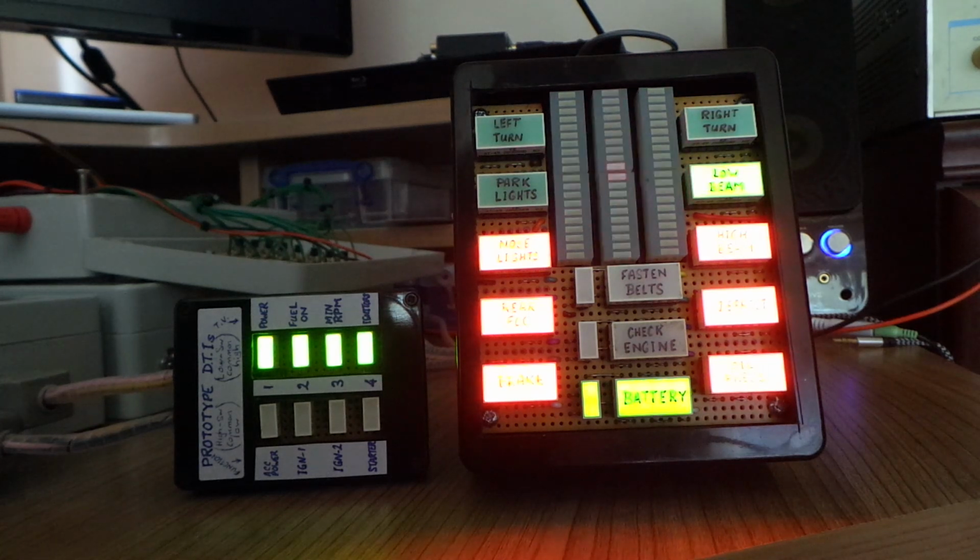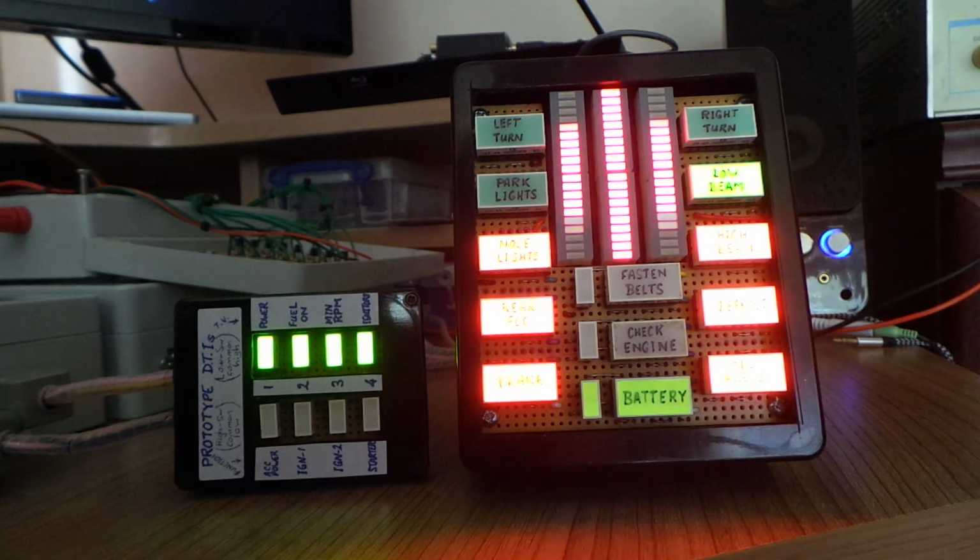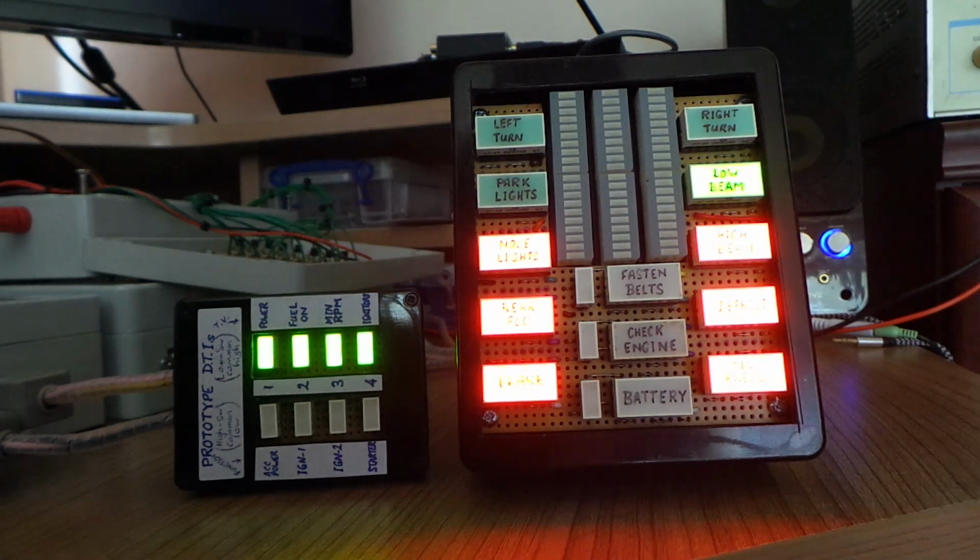So when you first put your ignition on and the engine isn't rotating, so the alternator's generating no voltage, you will see that battery indicator illuminate, because of course the alternator voltage is 0, but the battery voltage has some definite voltage. As the alternator starts to generate a voltage, it brings up the voltage it's generating, and when it eventually matches the battery voltage, the battery indicator will go out, as it should do most of the time.